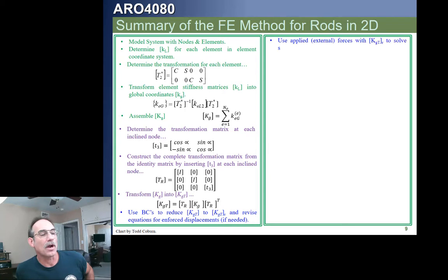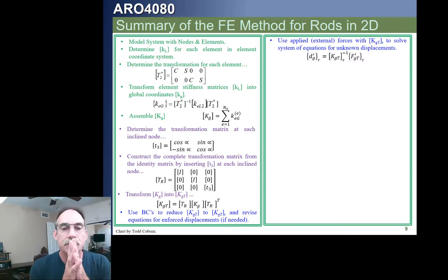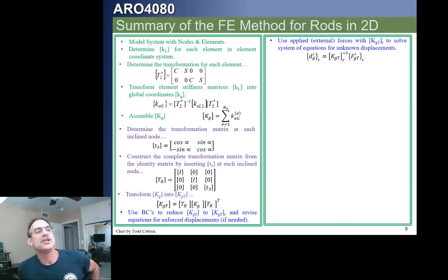Once we've done that, we're going to solve our reduced system of equations, using our external forces, to get our displacements in that reduced, transformed direction.